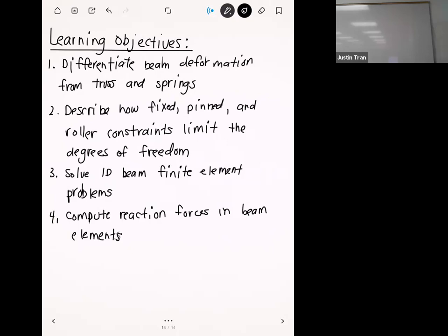So my thinking was the reason why both sides aren't as heavily affected is because here you have a drum striking downwards with the middle of the blade. But also you have a force that's acting parallel across the negative z direction. So you're having a force like this at the same time. So I figured it's somewhat reasonable, but then again I don't see how it's reasonable, because I would still expect to see a decent amount of stress concentration right here, at least some of that, but it's not.